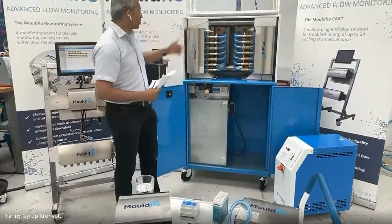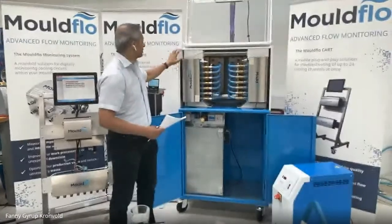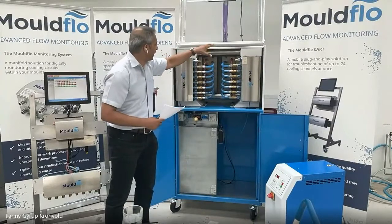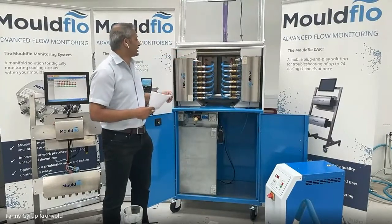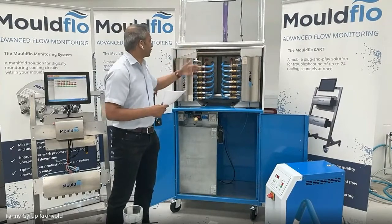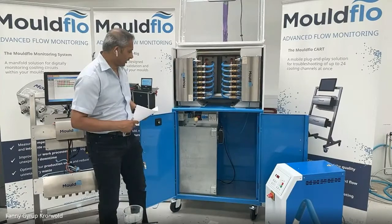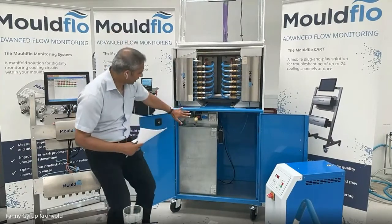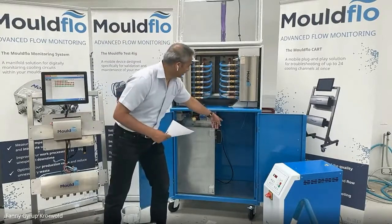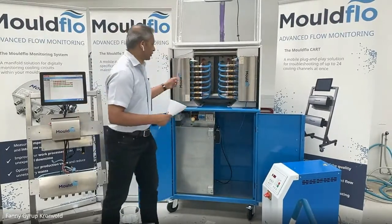In this box, you can see the manifolds are installed on the injection molding platens, left and right side, moving side and fixed side, and the hoses that supply the cooling water are connected, both inlet and outlet, to the manifold. Down here, you can see the control panels. That's where the power supply and the server are installed, and everything is connected with a serial communication cable to each of the manifolds.